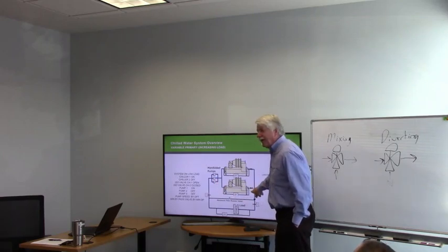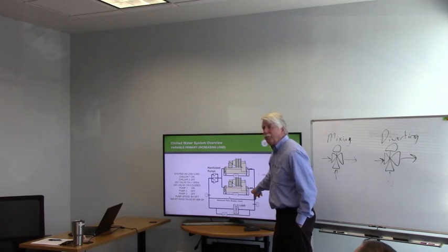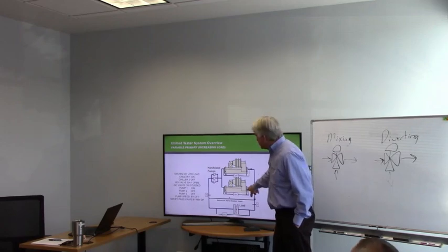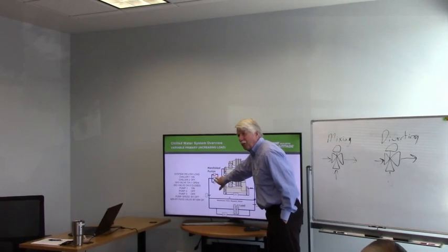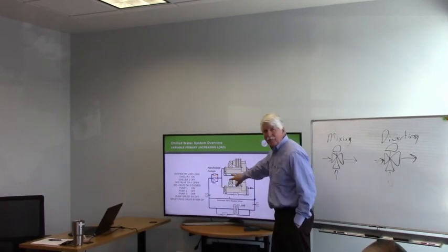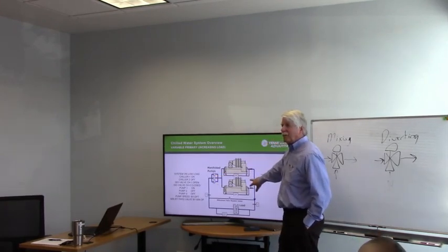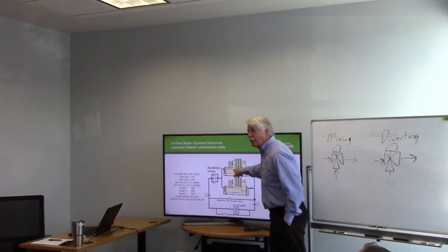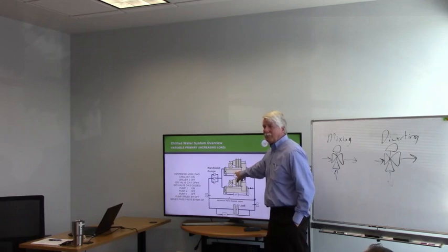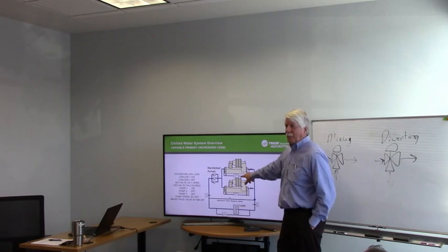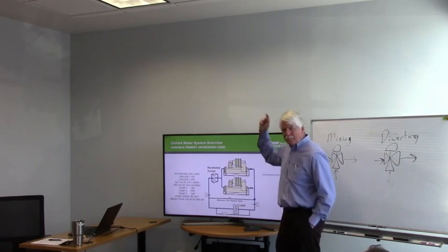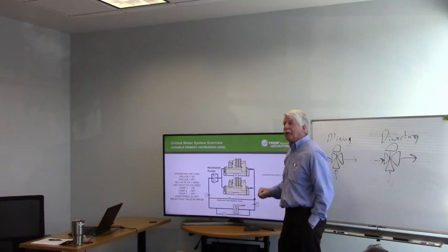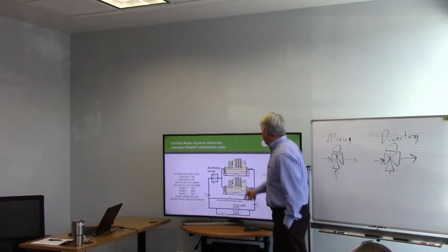When I open that valve, what happens? Suddenly, I split this flow from 800 GPM and gave it 2 paths. So immediately what's going to happen is I'm going to have 400 GPM going through this chiller, okay? And chances are very good it may experience a flow loss, okay? Because you just drop the GPM on it really quick, and you don't want to do that.